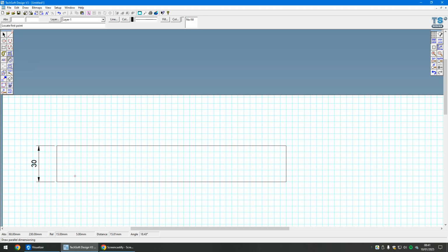Okay, I'm going to go back to the dimension line tool again, which is tool B5, and now I'm going to add a dimension on the bottom of the rectangle of my ruler. So I'm going to click on this bottom left corner once, click on this bottom right corner once, and then bring my mouse into the middle, and then click a third time, and that now defines that the length of this ruler is 190. Okay, absolutely fantastic.